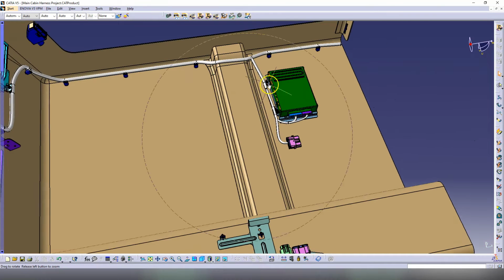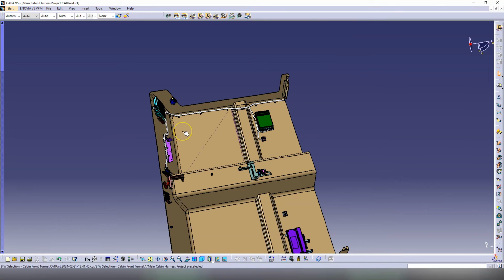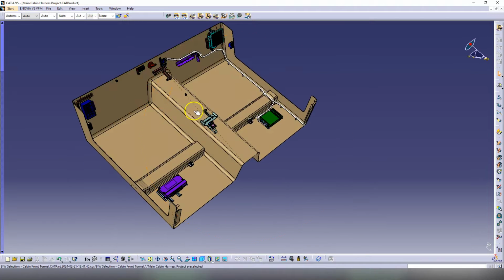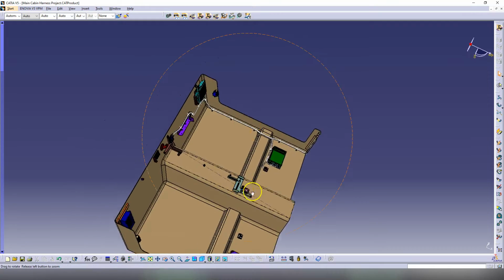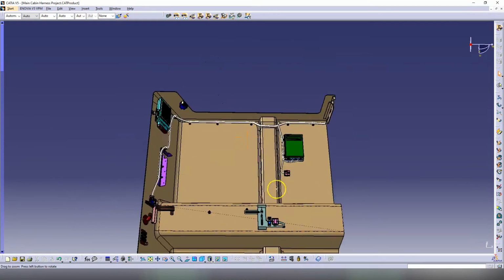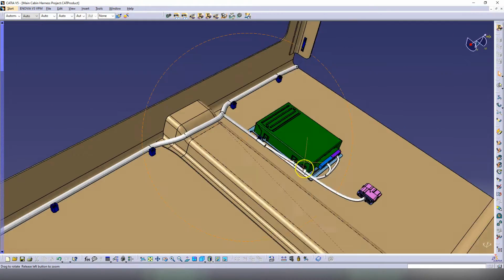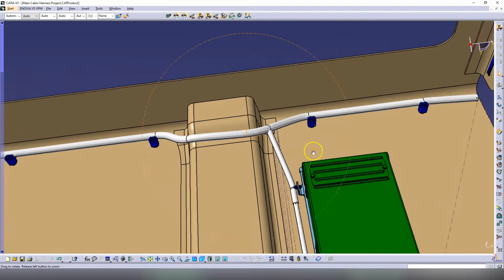You need to take the whole harness and just do it from scratch for a left-hand drive vehicle or for a right-hand drive vehicle, because all the components are going to be reversed. Components that you have here are going to be on this other side, and so on. All those sensors for the pedals and the gearbox and everything. Diesel and petrol, they are different harnesses.